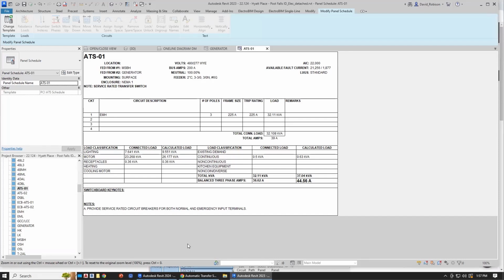We'd like to show the schedule for the transformer, to make sure that the transformer size is correct in relation to the load that's coming on the transformer. For me, it's just a good check to make sure that we're not oversized or undersized on the transformer, or really close, but we have not been able to correctly model in a schedule.